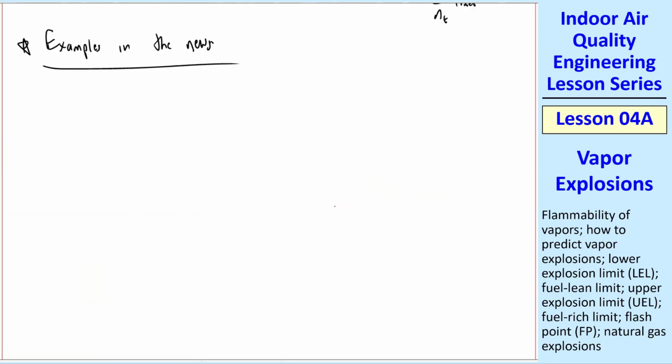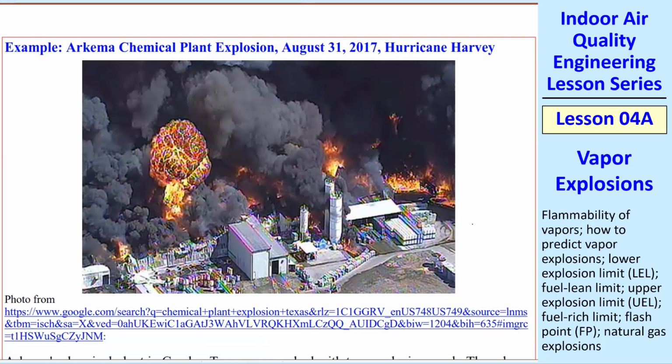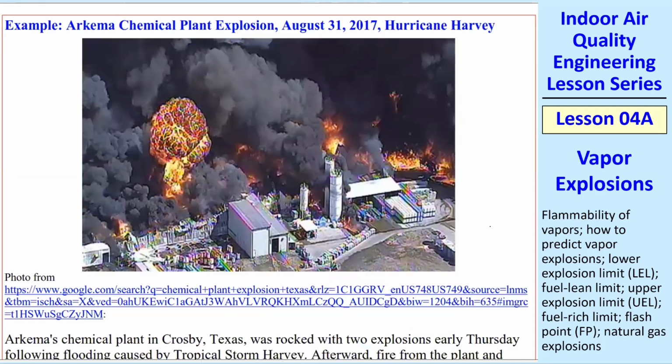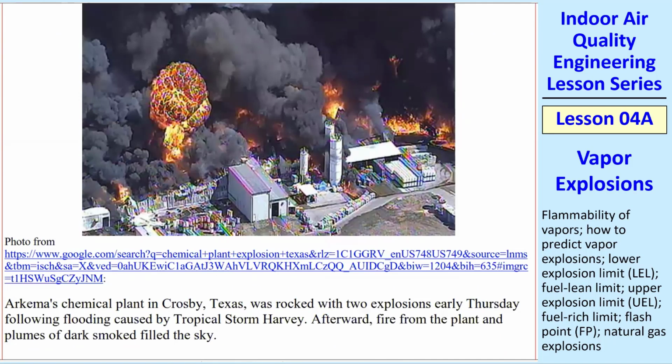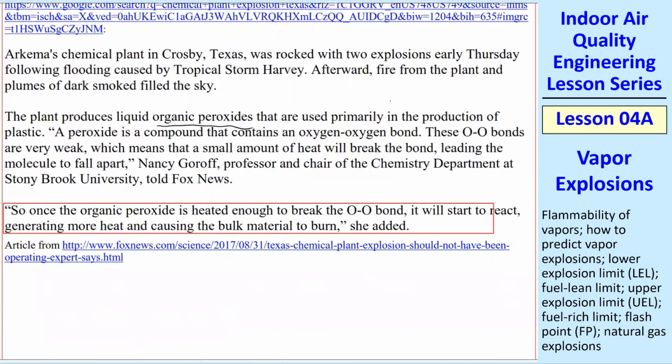You hear it on the news if you watch the news. There was one actually right around when I taught this lecture back in 2017 when Hurricane Harvey hit. There was a chemical plant explosion, and I remember a couple days leading up to this, everyone said this is going to explode. They had some nasty organic peroxides in there. This is the case that I was talking about before, where you have a liquid stored in a tank and it was below the flash point.